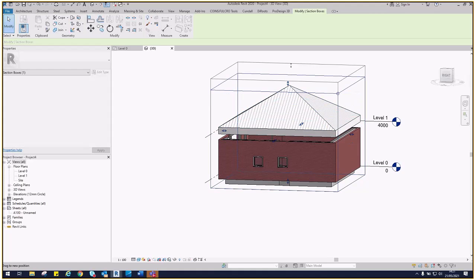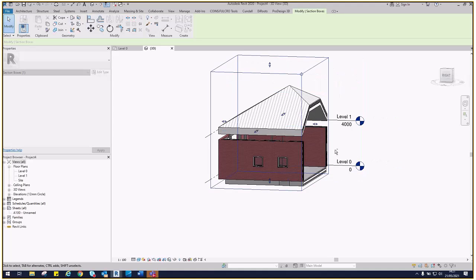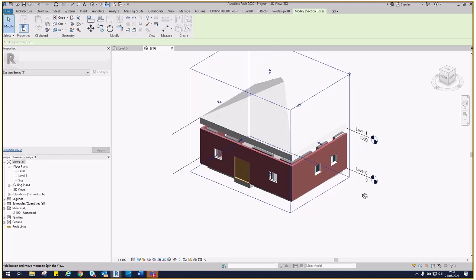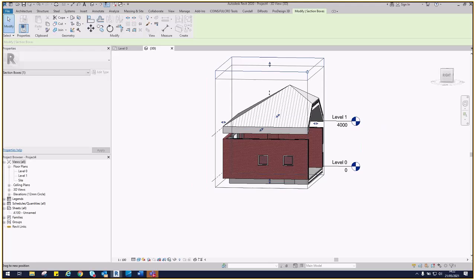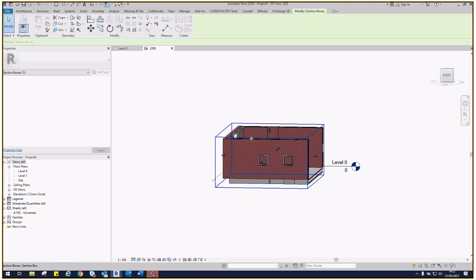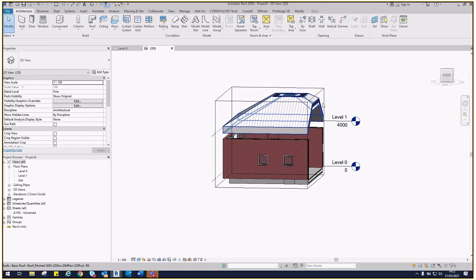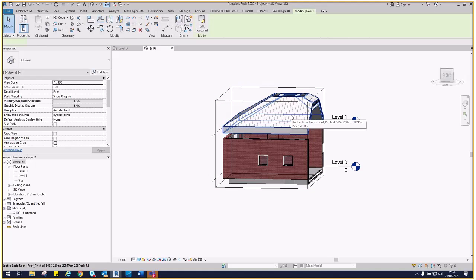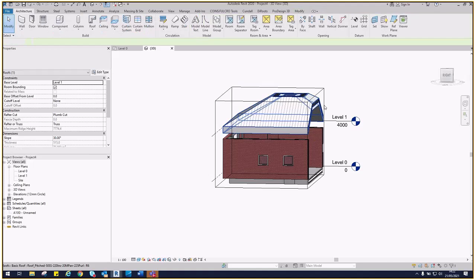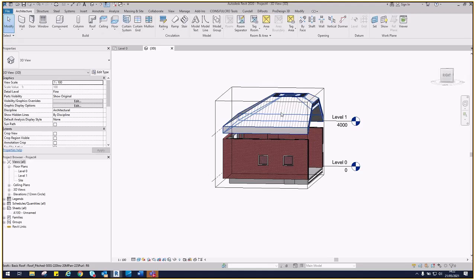So when we're in the 3D view, there is a section that we can start to pull off various different elements. So we can move this section so we can start to see inside the building by simply clicking a box. What had happened just a moment ago, the section box was right down at the bottom, and therefore it was missing the roof area. Because we've drawn it twice, I'd imagine we do have 2 roofs. So if I left click and hit delete, that deletes one of the roofs. There we go, you can see that there was 2 roofs and now the one is still there.